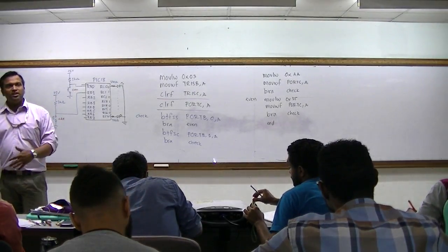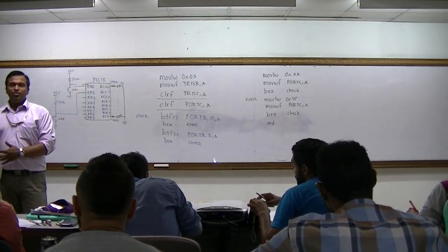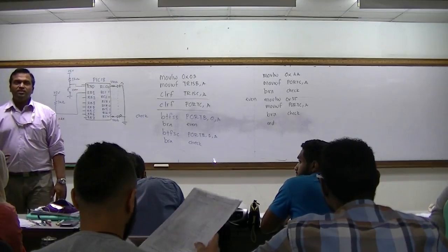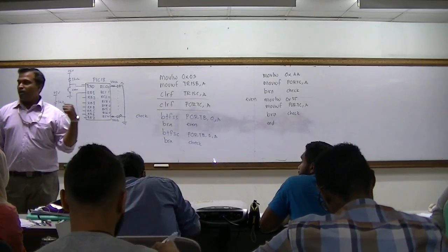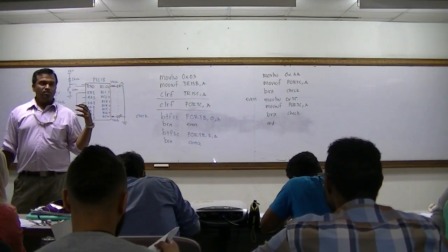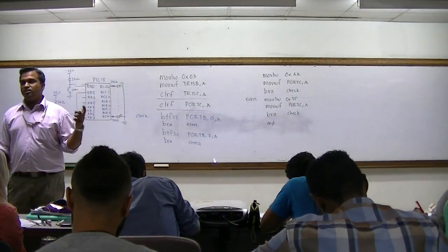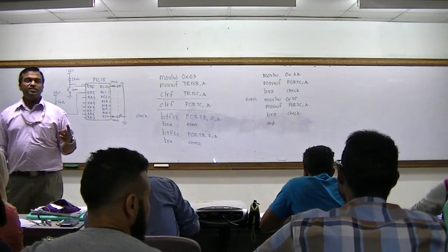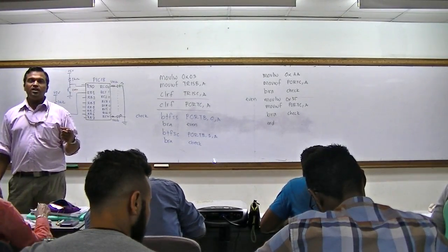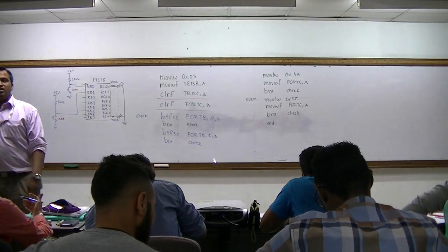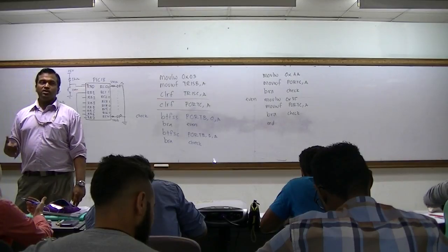You can move a literal value, you can move W to F, you can read it like a normal file register. And then about interfacing. For the switch, there's only one type of interfacing, one configuration. When you're not pressing the switch, it's logic 1, when you press it's logic 0. There are 3 methods of interfacing the LEDs. One is if you provide logic 1, another is if you provide logic 0. The third one is when you're having the NOT, you have to provide logic 1.